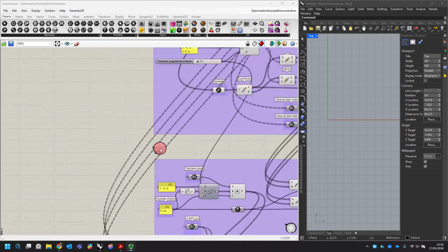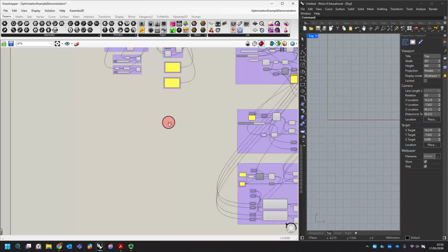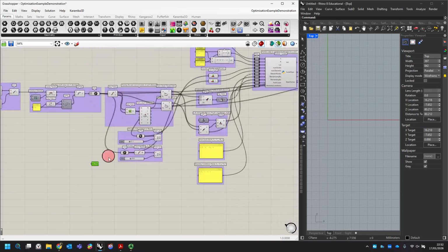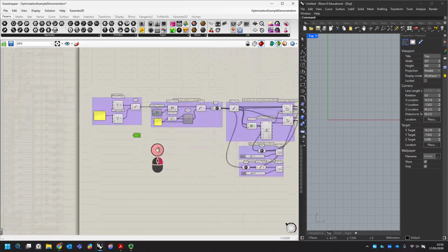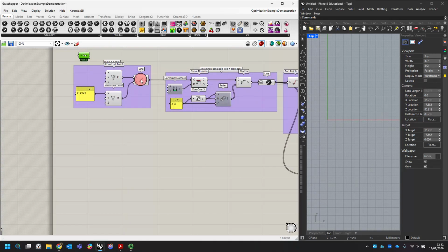So I'm just going to move the bifocals over, and we're interested, as I say, first of all, in going back to the beginning, where we're actually generating everything. So what we want to do is split our original line at particular locations, and they're going to be the locations of the supports, but also the location of that central loading. So that's what we'll do in just a second.